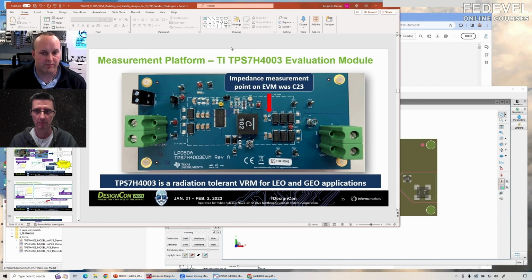Yes, but the problem is, LTspice is a great example. Even TI's tools are great. The problem is all of those have fidelity gaps. How do you include the port effects? How do you include those additional parasitics that actually affect your power supply performance? And this is a huge gap in the industry.